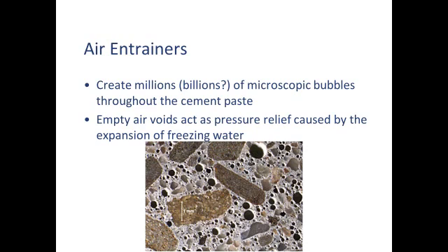And they act like a pressure relief, so that as water freezes and expands, it doesn't all happen instantaneously. These empty bubbles act like a reservoir or pressure relief to let the water move into. So as the ice expands and pushes away the liquid water, that liquid water has a place to go. And when the concrete thaws, the air pressure that's inside that little bubble pushes the water back out. So there are little pressure relief chambers like shock absorbers.